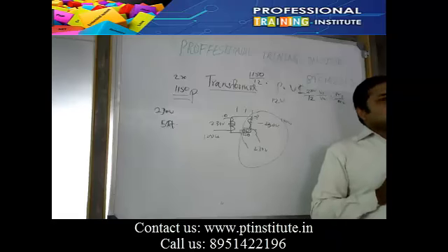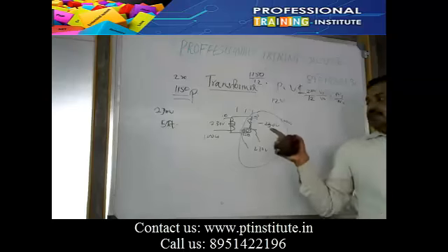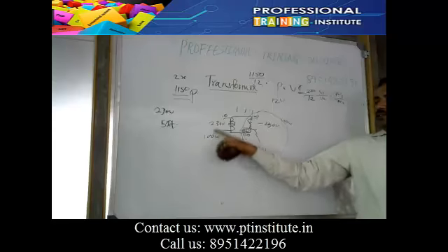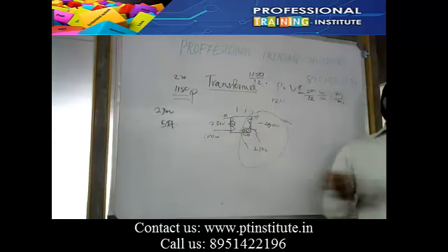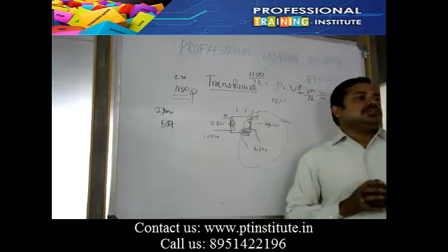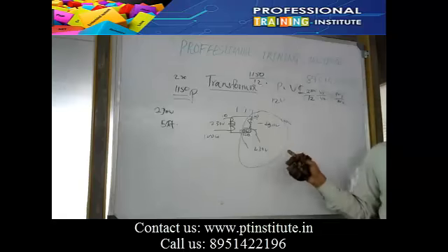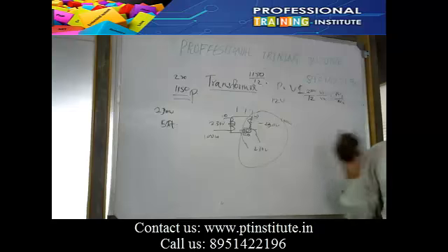The voltage is the same, but current capacity he won't have. Consider if he is having a current capacity of 5 ampere, both together can draw a maximum of 5 ampere, not more than that. This is for 1:1 number of turns. Unity 1:2, then also power will be the same. Current can vary, but power will be the same.